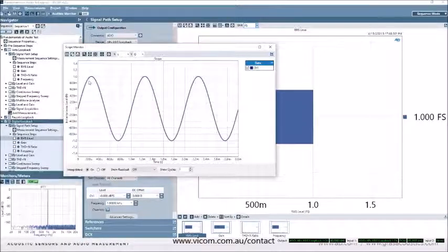So whereas with volts or pascals, the same underlying unit represents the signal both in its RMS, or root mean square, quantity or in its instantaneous value form, in the digital domain, we have two different units and they are not directly interchangeable.